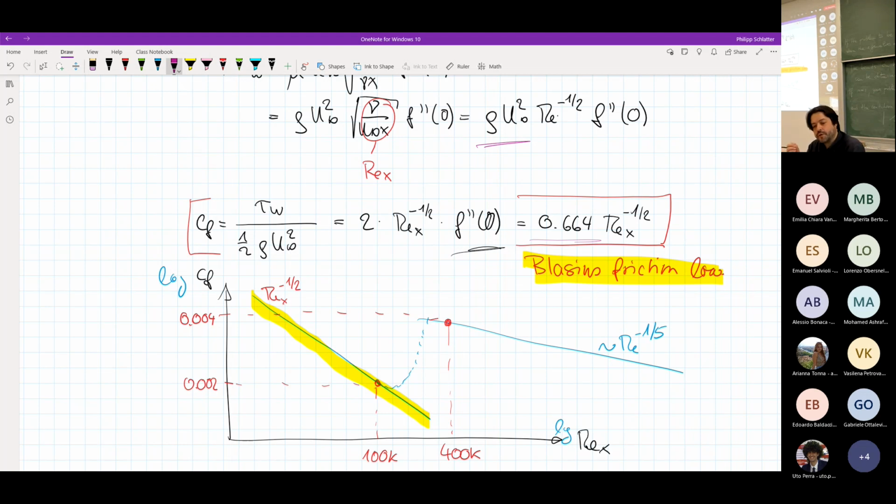The idea of momentum loss is exactly a measure for the friction that you would have, because if you have the boundary layer losing momentum because of the growth of the boundary layer, through the action of the no slip boundary condition, that of course is exactly what, in the form of a force balance, causes the friction at the wall. So momentum loss and friction are two sides of the same thing.